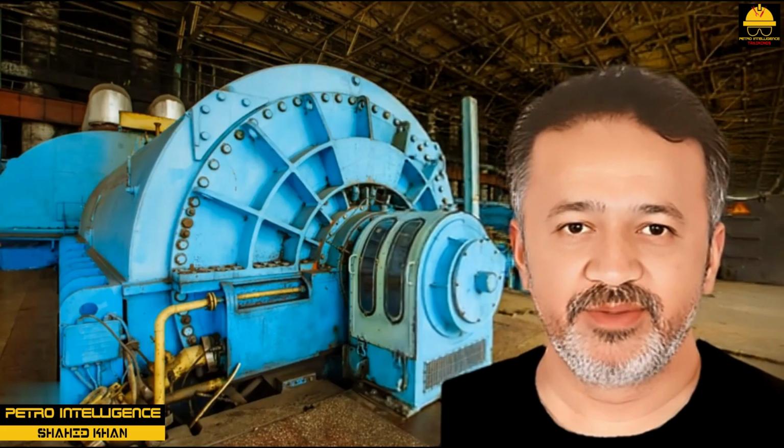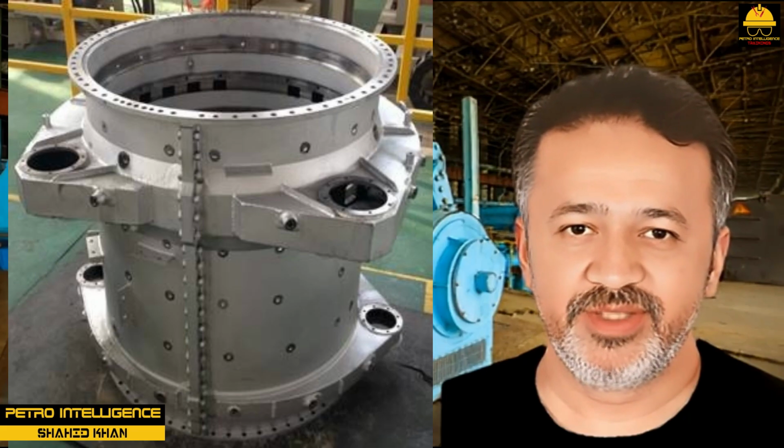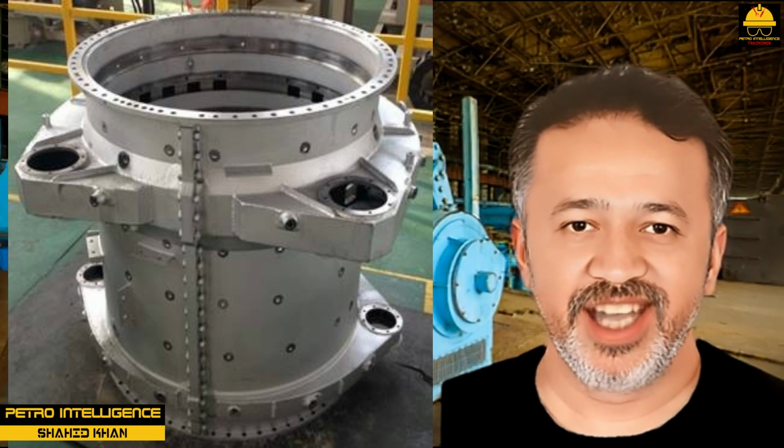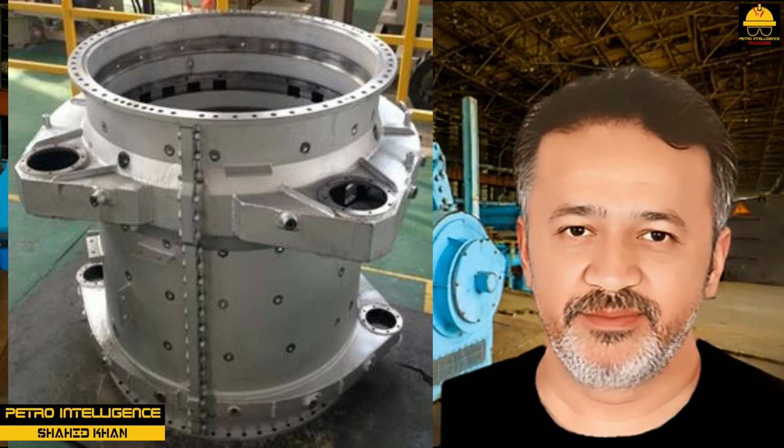Casing. The casing is composed of a base and covering made of carbon steel or turbine iron. The base and the covering are designed to form steam-tight joints. Gaskets typically are not needed when reinforced flanges are used.